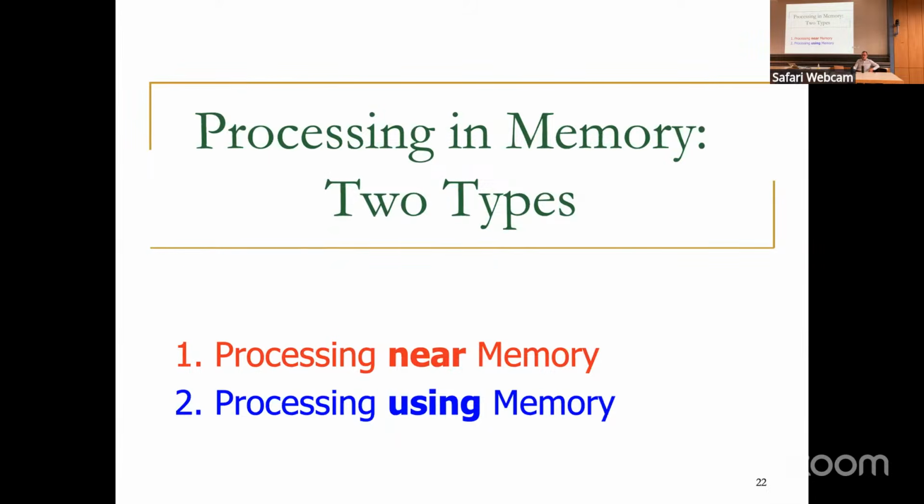The second is FPGAs. Are they considered processing in memory? So it depends on what part of FPGA, right? FPGAs have lookup tables, and lookup tables are a mechanism of using memory to actually do computation. Yes, that part, yes, but maybe not everything in FPGAs. Does that make sense? So lookup table-based computation is fundamentally about, assuming it's implemented with memory structures, which it usually is actually, you look up tables. It's using memory structure to do computation.